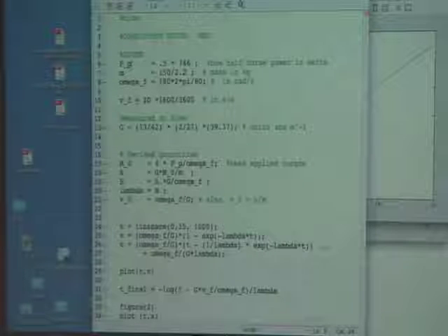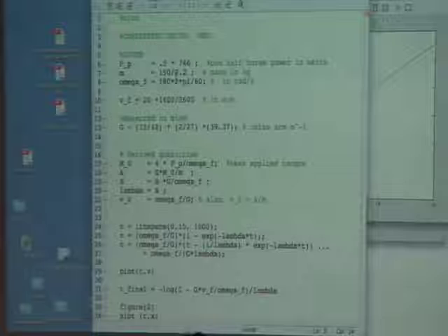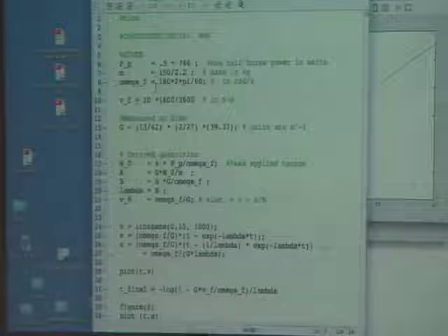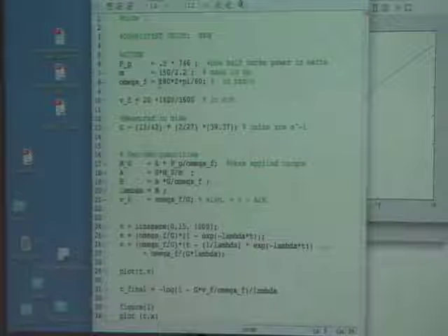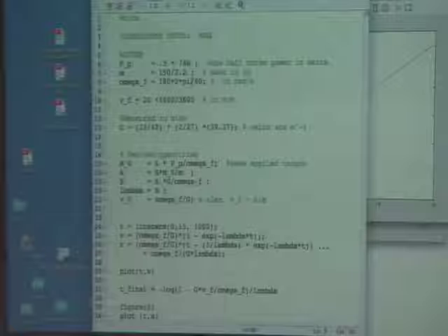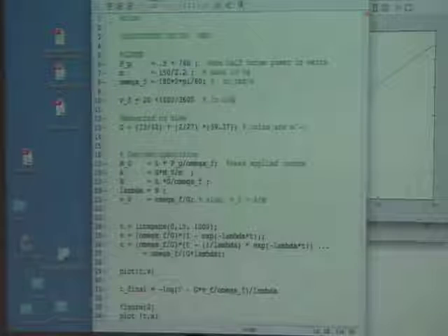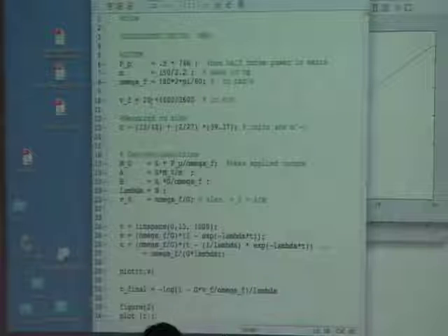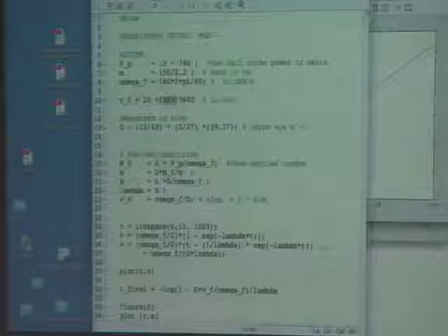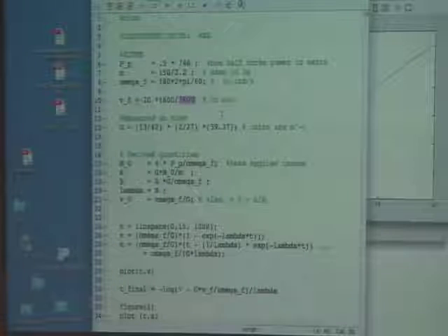Okay, so I'm going to do MKS, which I'm sure most of you prefer. We have the mass in kilograms as 150 divided by 2.2. We have the angular velocity given as 180 RPM. RPM is revolutions per minute. We need to multiply by 2 pi to make that radians per minute, divide by 60 to make it radians per second. We were given that the final velocity we're interested in solving for was 20 miles per hour. We multiply by 1,600 to get that in meters per hour, divide that by 3,600 to get that into meters per second.